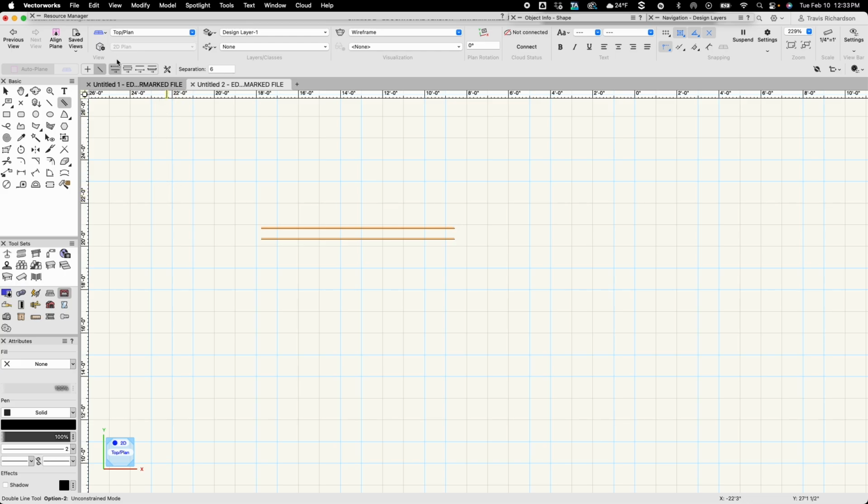And there are some additional modes right next to that over here, and they control how the lines get drawn. The first one is left control line mode, which means your cursor is going to go along the left side of what you're drawing, kind of like so. Next one is going to be center.